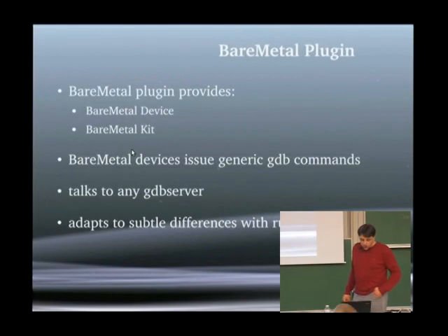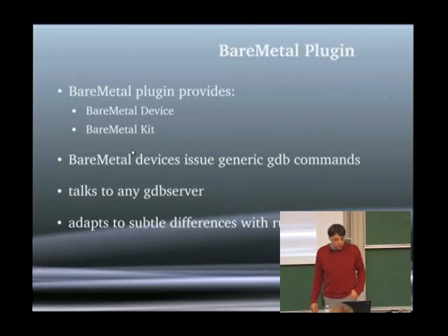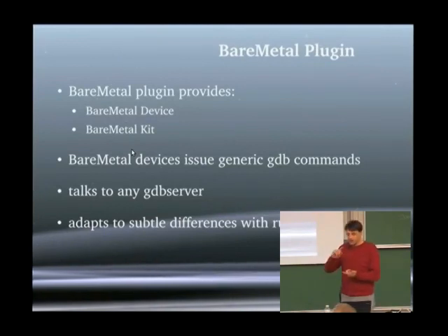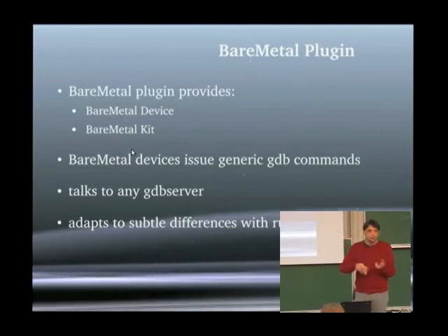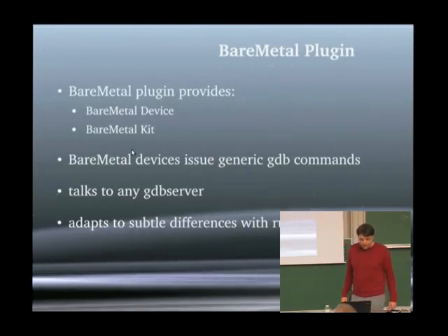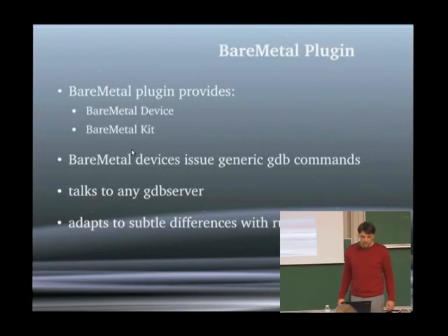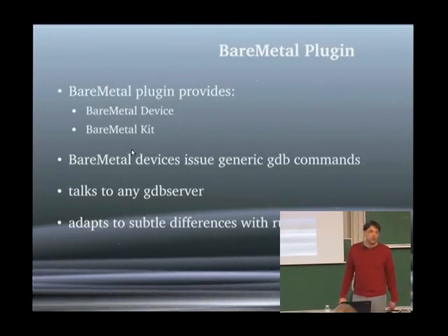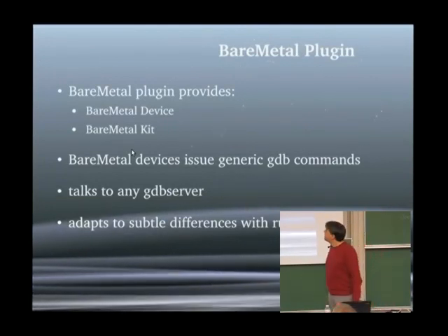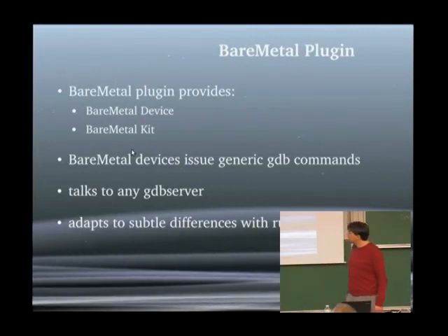Yeah, one thing that was missing in QtCreator was the bare metal stuff. So it has nearly everything in place: the compiler support, debugger support, nice code completion. But one thing that was missing was that it was not able to directly talk to a hardware GDB server, which has some subtle differences in the way it has to be talked to. And that's why I wrote the BareMetal plugin for QtCreator.